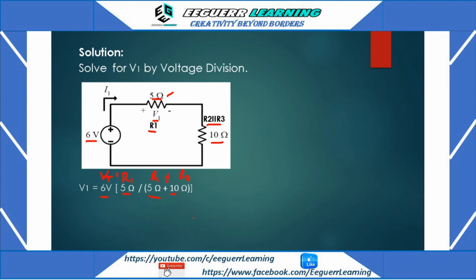So solving for V1, we will be needing the voltage division or the voltage divider principles for that. And that is V1 is equal to voltage total times R1 divided by R1 plus R2. That should be the formula.